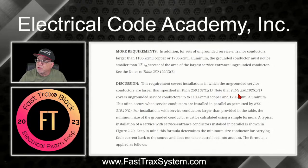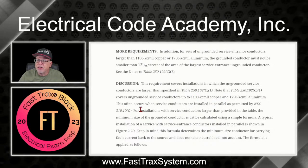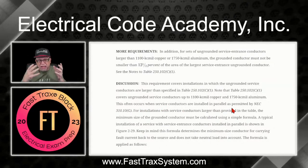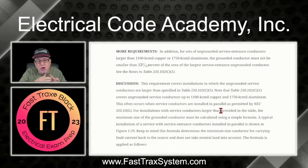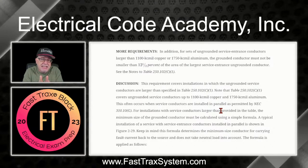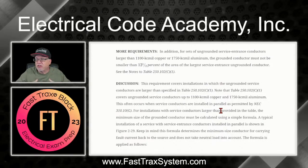Note that table 250.102(C)(1) covers ungrounded service conductors up to 1100 kcmil copper and 1750 aluminum. This often occurs when service conductors are installed in parallel because you're trying to get more amps, so you want to have smaller conductors to run, so you're going to break them out into parallel sets. And that way you get to use the ampacity from each conductor acting together. So if you had two parallels of, let's say, 500s that were 380 apiece, then you add them together in parallel, and you get 380 times 2.